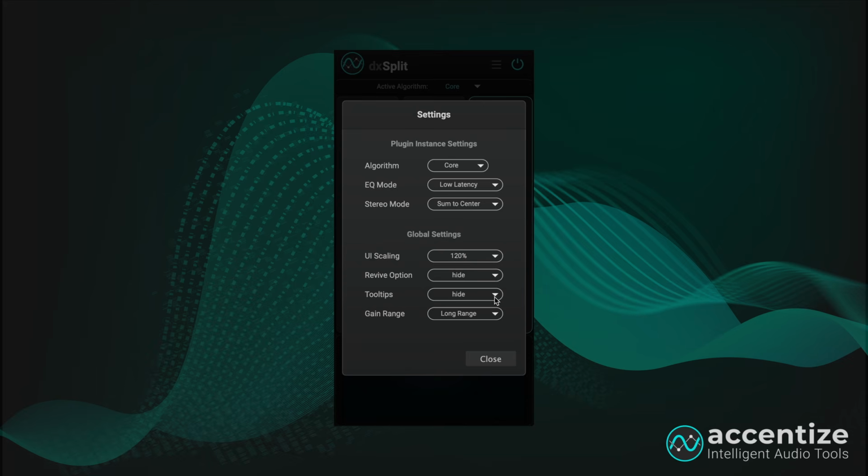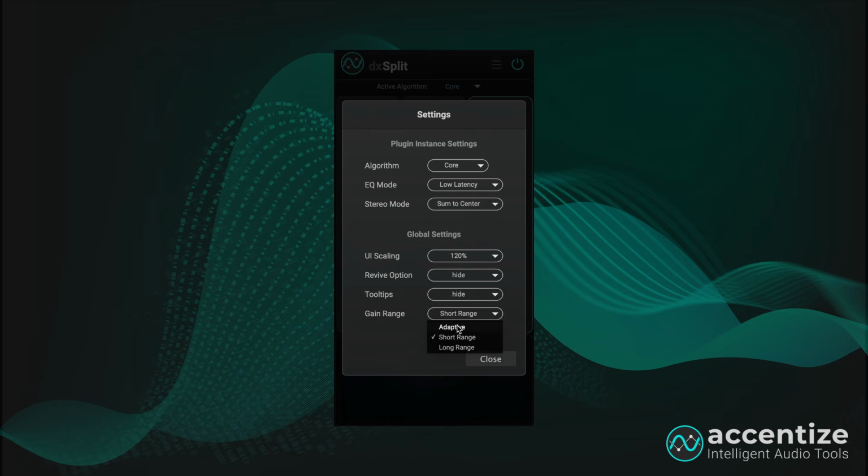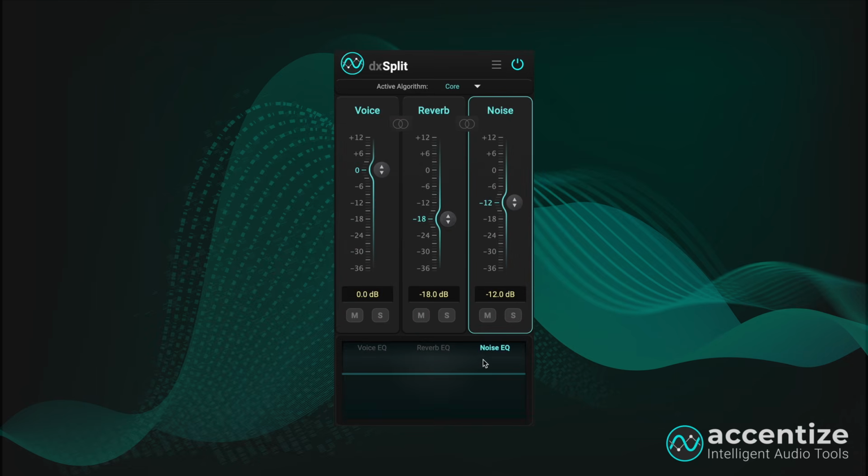Below that, you can activate or deactivate tooltips, which appear when hovering over controls in the plugin window and explain the different functionalities. Finally, you can set the gain range to short range, long range, or adaptive. This defines the resolution of the gain scale on the main mixing sliders. In short range mode, the sliders show values down to -18 dB. In long range mode, they extend down to -36 dB, with -infinity at the bottom. In adaptive mode, the range automatically adjusts depending on the slider position.